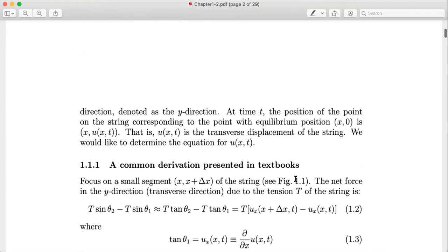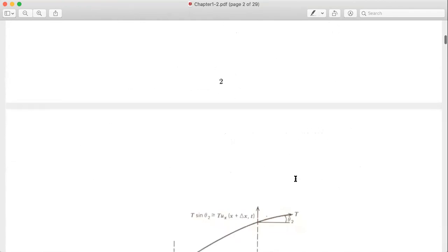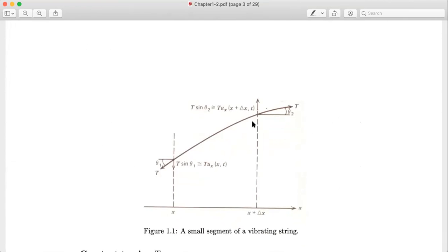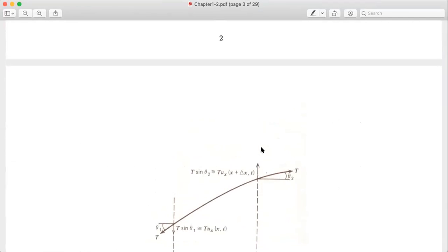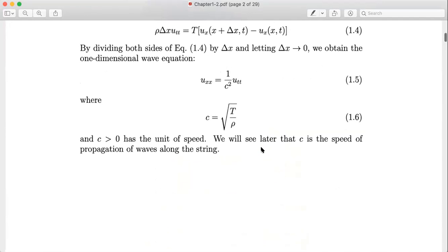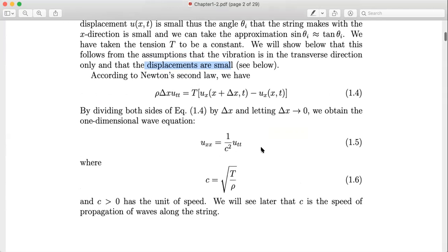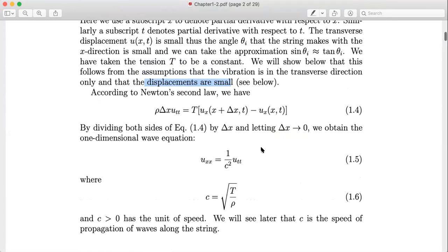So that's the standard technique of deriving the equation of motion for a continuous system. We look at a small segment, delta x, and then eventually let it go to 0. We will see this trick many, many times later, particularly also in deriving equations for fluid motion. In that case, we will take a small region, or we call it a fluid element, a delta volume. In any case, let delta x tend to 0, then you put delta x to the other side.